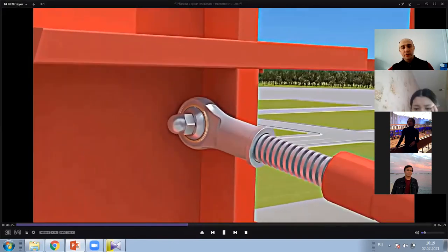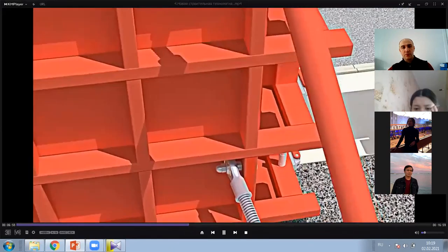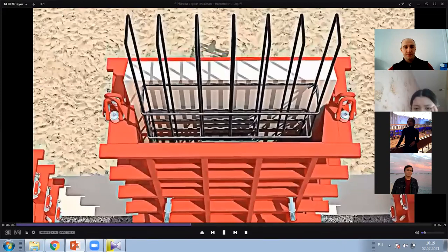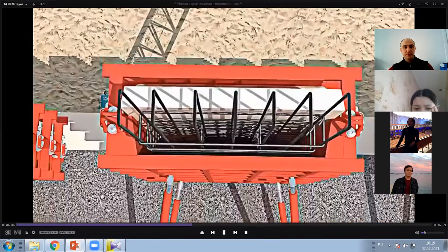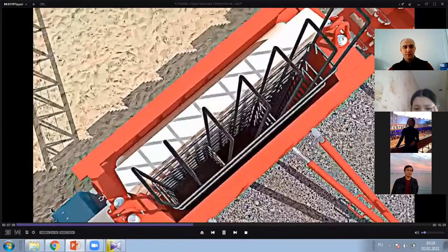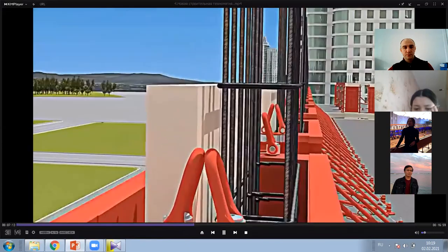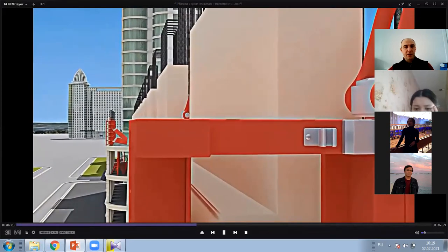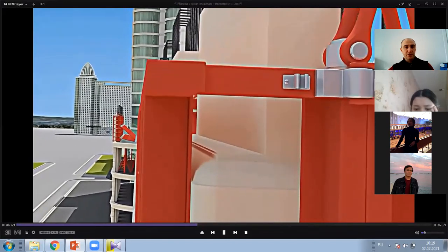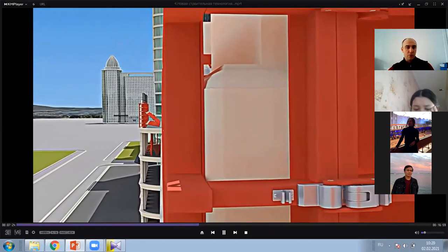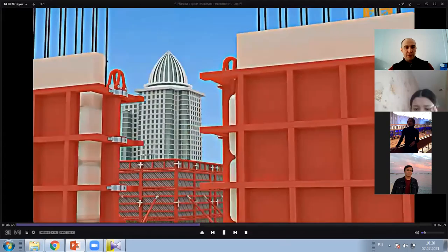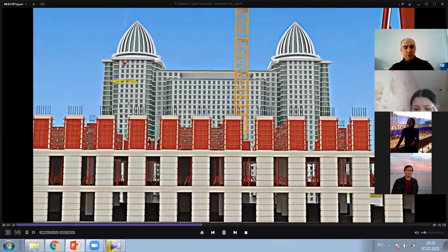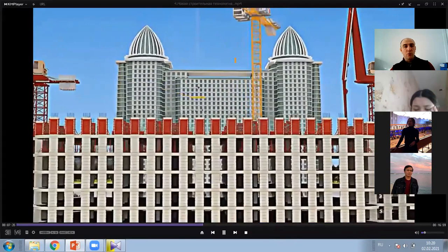So to avoid any type of problems, of course, all joints should be checked well. So the verticality and horizontality are checked, you see that all formwork is standing in the right position according to each other, according to the levels located below.